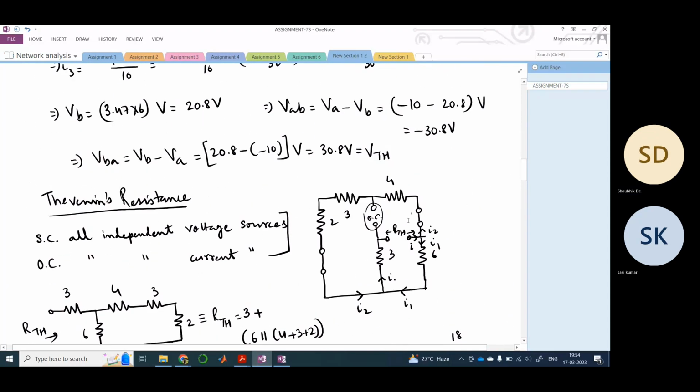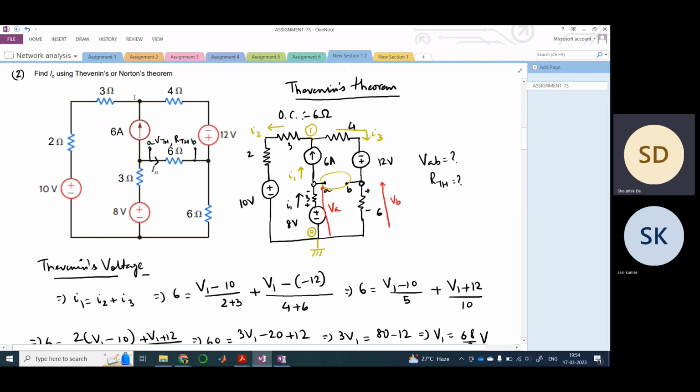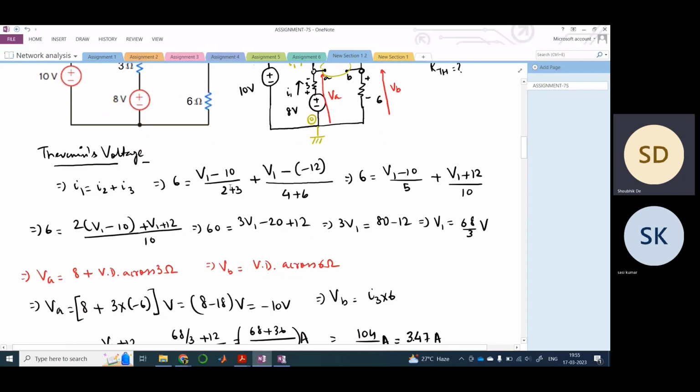You can see that the problem is lengthy to some extent, right? But it would have been more lengthy if you would have calculated this using KCL or KVL, because in KCL there would be so many nodes, and in KVL there would be three meshes, but again you have so many voltage sources and one single current source, right? So it would make the circuit complex.